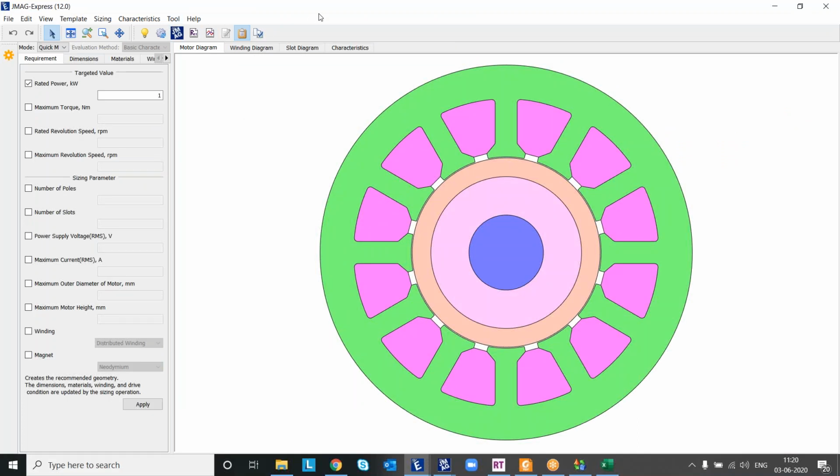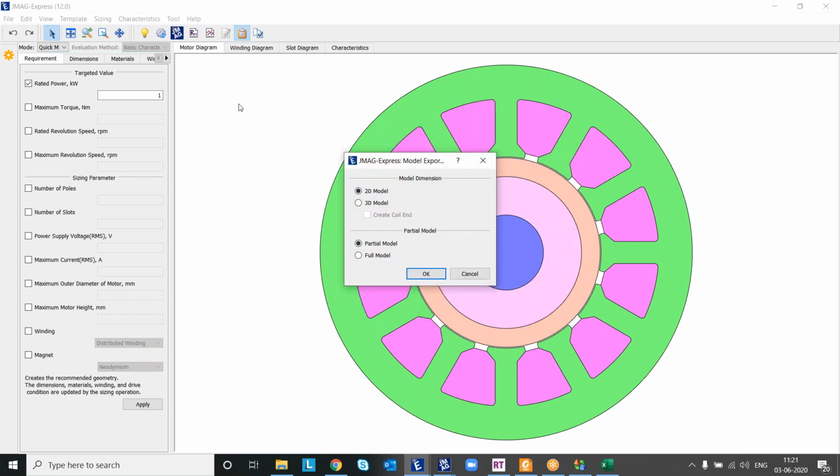And coming to the designer. The designer is the FEA tool for detailed analysis of your particular model. There you can discretize your entire model into triangular or tetrahedral elements. For each component, we will have different machines, and we will be analyzing them in the tool. Here you can see a button called calculate in designer. When I click on it, it will create a link between JMAG Express and JMAG Designer, which eases our operations of creating a model in JMAG Designer.